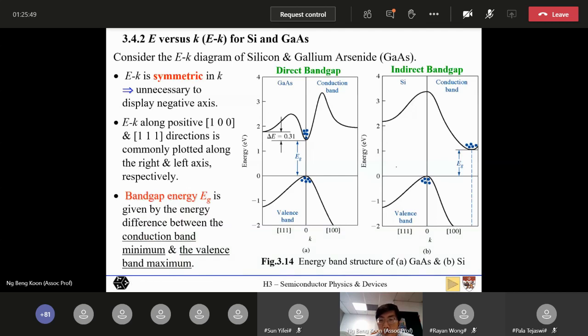So it turns out that in a practical semiconductor, you actually get defect levels in the band gap, because of imperfections in the crystal. If we have a pure, nice crystal with no defects, then the band diagram will look like this. But if you have imperfection, like for example, at some location an atom is missing in the lattice, or there's an extra atom in between the lattice, this will actually introduce additional energy levels in the band gap, which we call defects.